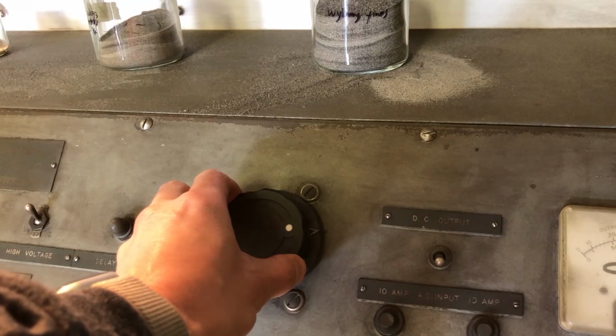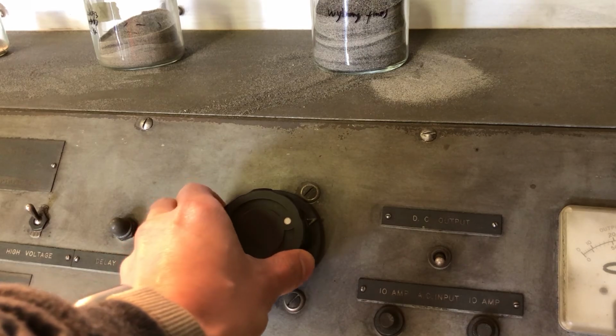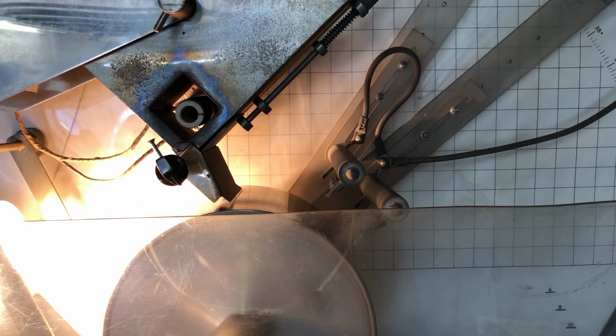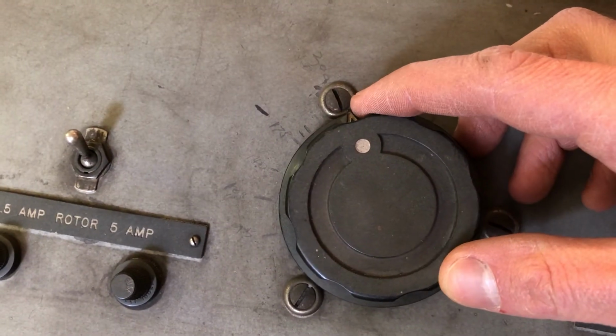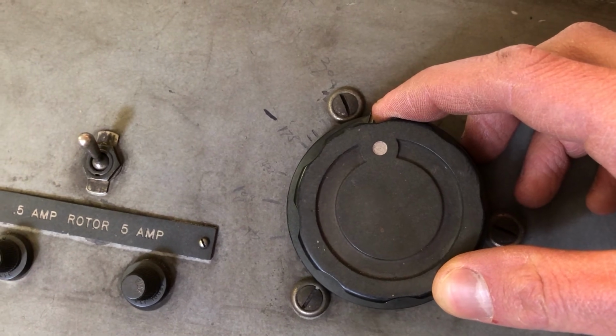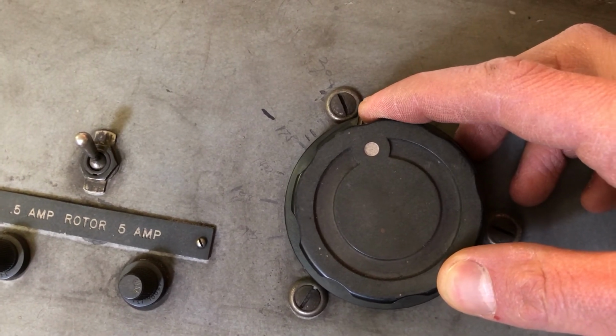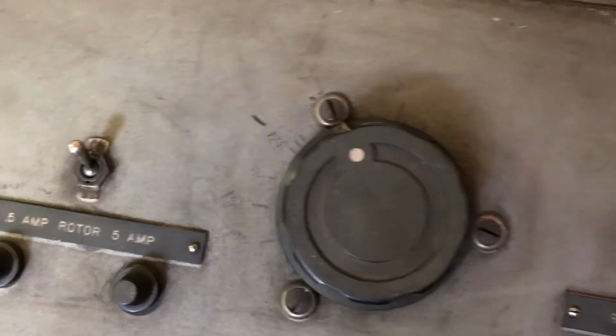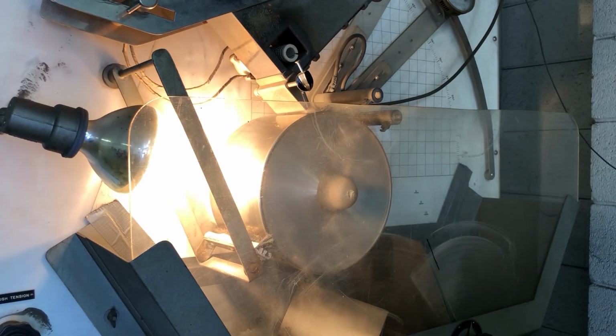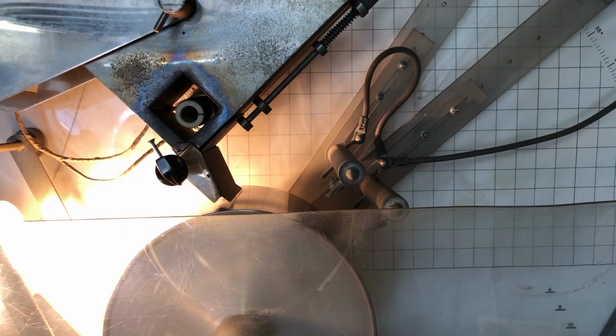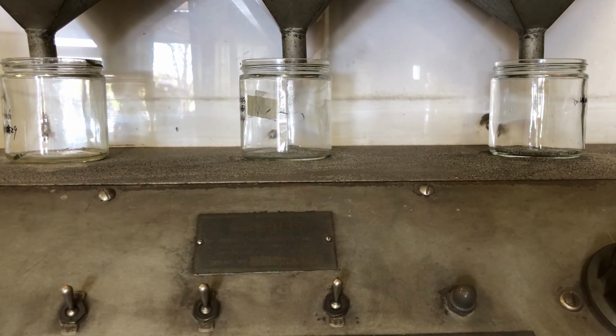We also have some arcing, so I'm going to turn the electrical potential down. I played with the rotor speed a little to try and throw the titanium particles further, but it's hard to see them, so I didn't change it too much. I don't want to throw too much gangue over the splitter. I left the splitter a little below the mark that was drawn on there. I'll trust whoever drew it. Now we just collect their samples.